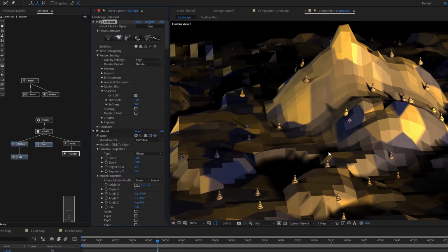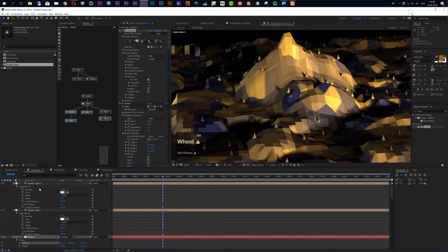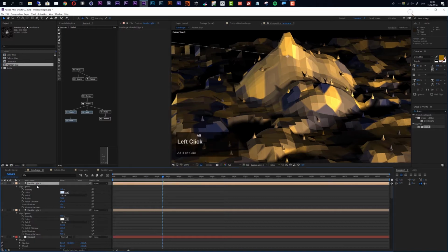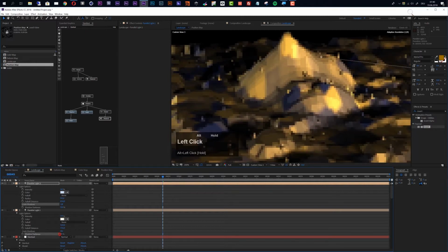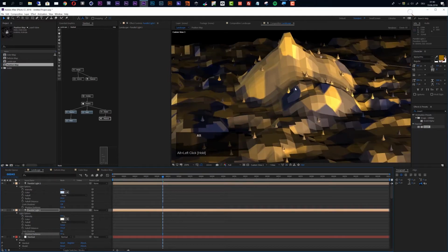You can also control the shadow by the lights, of course. So right now, both of my lights are creating shadows. And if I do not want this, so maybe I do not want this backlight here to create any shadows, then I can just turn off the cast shadows in this light. And I can also change the shadow darkness in my light settings here. If I change the shadow darkness here, you see that my shadows now are brighter and not so obvious. So let's set this to maybe 75%, and now I have really nice shadows.